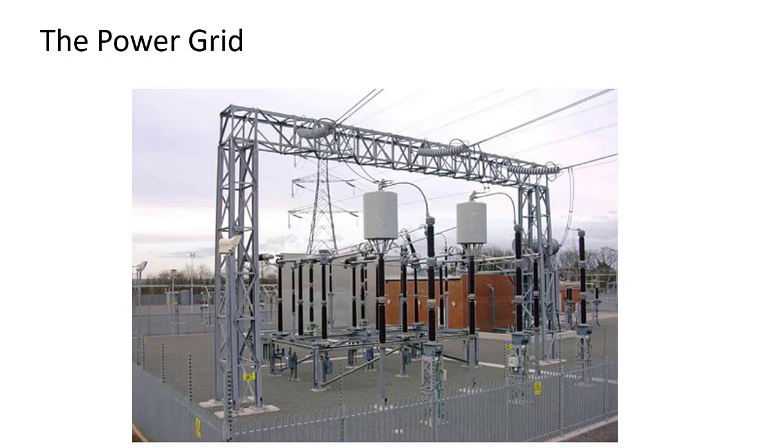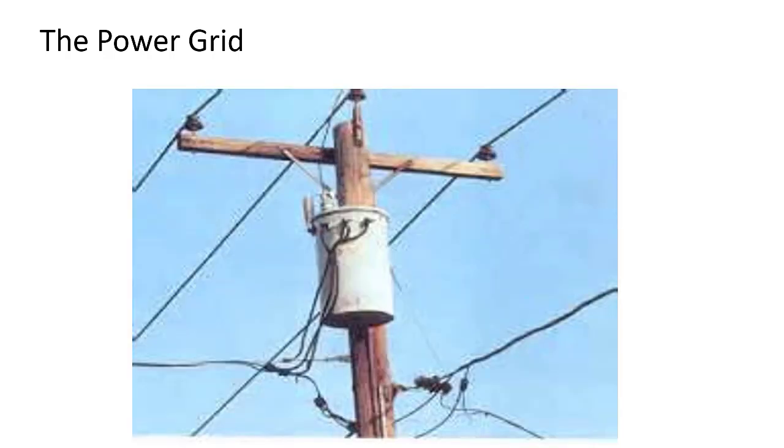These substations can be scattered all around a city or a county, and electricity is either split off to another substation or distributed directly to your home or business. However, before it can go into your home, it needs to be converted from three-phase electricity to split single-phase and reduced from 7,200 volts to 240 volts.